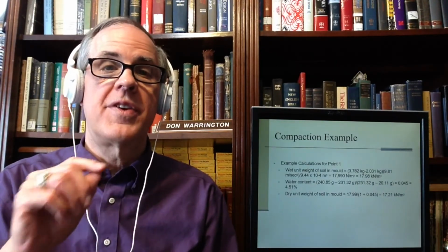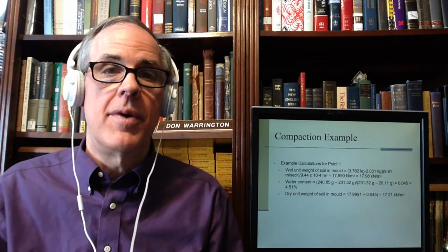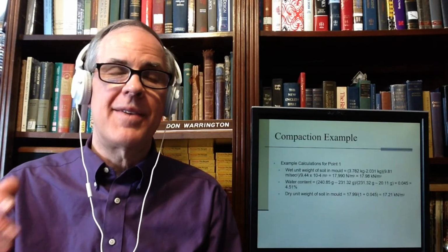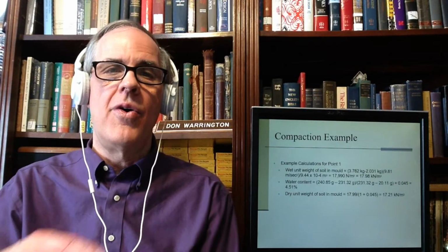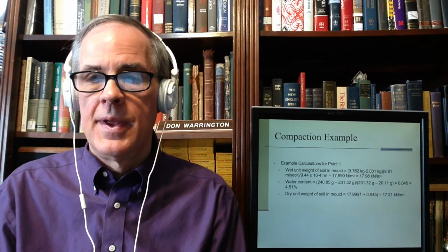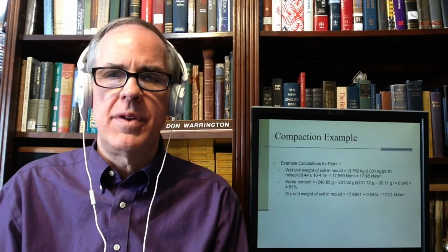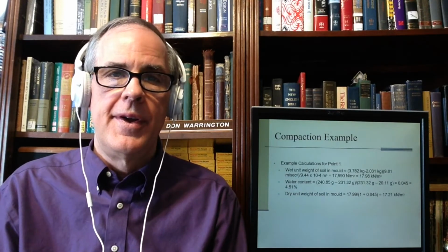Don't forget, before you dig the little sample out, to weigh your mold after you've compacted it. That keeps you from having to go into the mess of drying the whole sample, all that soil, almost 1.5 or 2 kilos of soil. That takes a long time. It's a time saver.